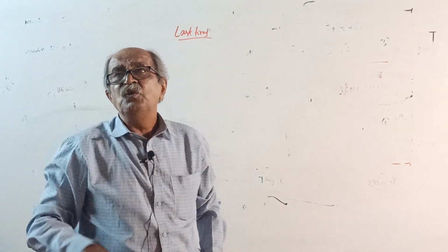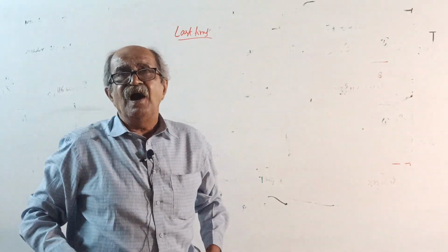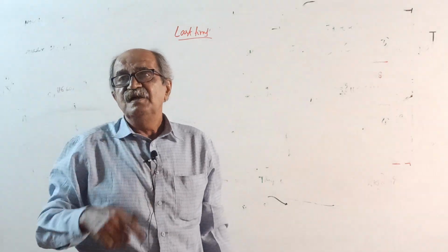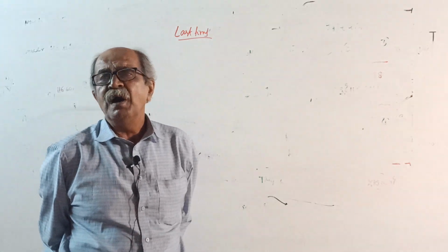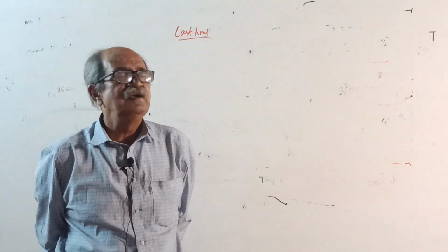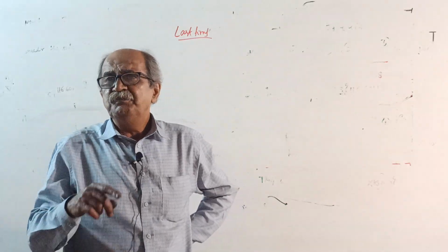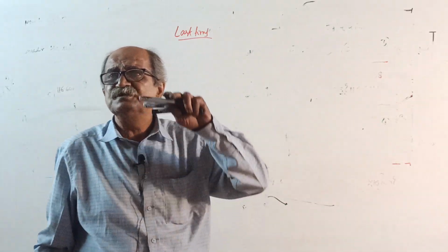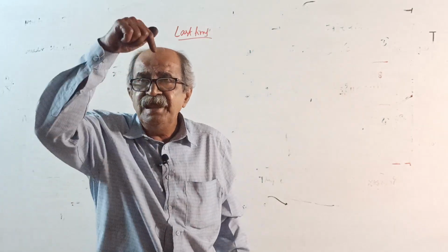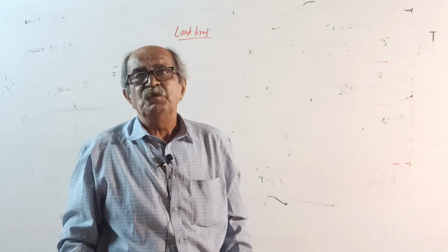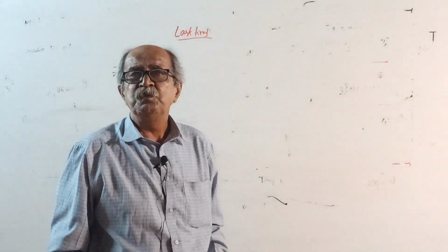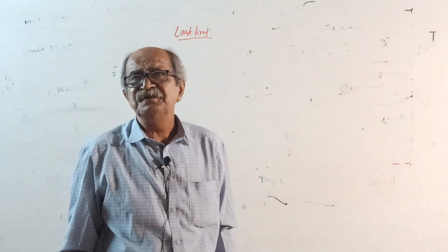If I about centroidal axis is asked in the question, then locate the centroid and mark XX, YY in red color. Find Ixx, Iyy. And if they also ask I about some other axis in the same question, then when you find Ixx, Iyy, divide into parts, each part you have to consider separately.